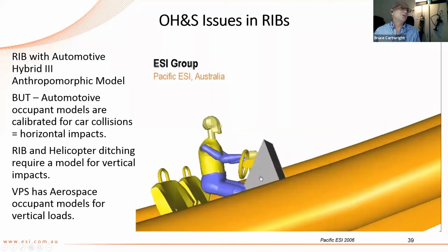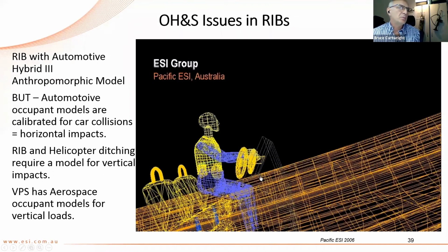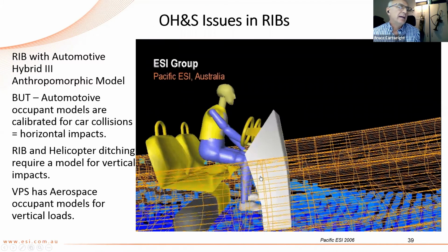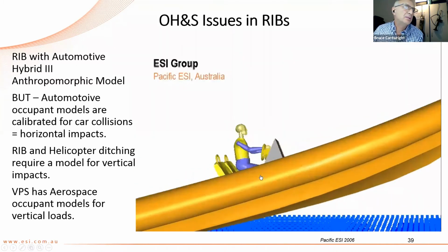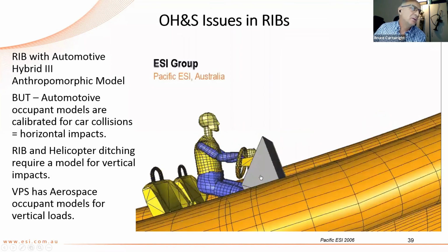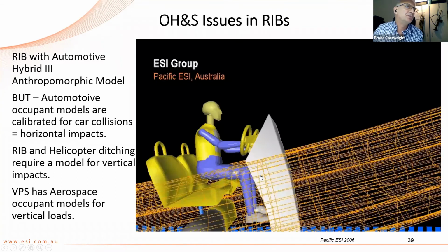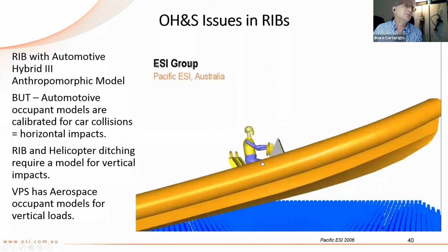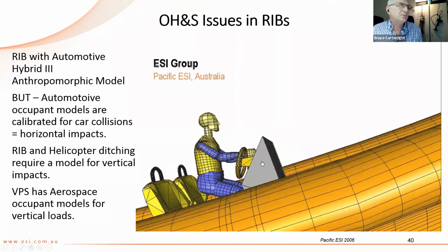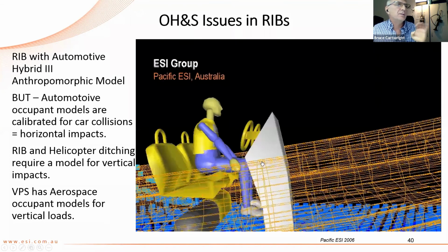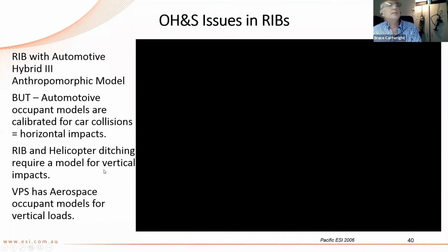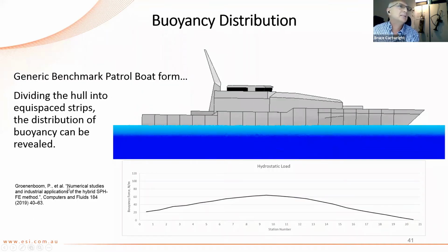Okay, here we go. So this is one of our crash test dummies from the automotive industry. And you can see it's got articulated joints, and the seats also are sprung to some degree. And this was going to be a comparison between a rigid seat and an impact absorbing seat, just to show the difference in behavior. And being a crash test dummy out of the automotive field, there's sensors all over that model, so you can get the compressive load on the spine. And it will be interesting just to demonstrate how that changes with an impact absorbing seat.